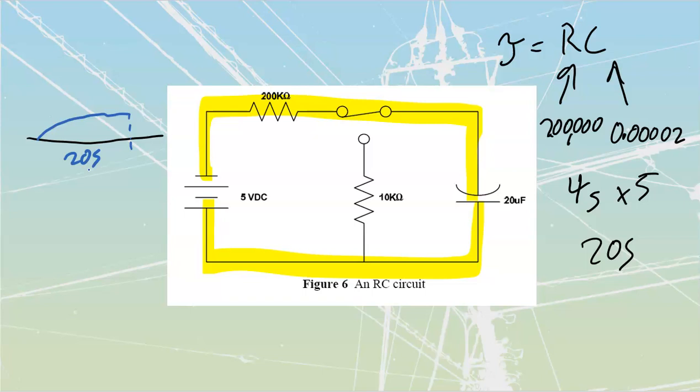So, what would the voltage be after 4 seconds? Every 4 seconds is going to be a single time constant, so we're going to be rising by 0.632. Inside of your book, they show this thing as being 3.16. That is a single time constant that they are putting in on that book. It's errata under example number 2. Don't trust it. Let's go and take a look at our graphs.